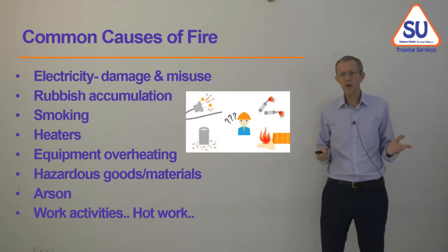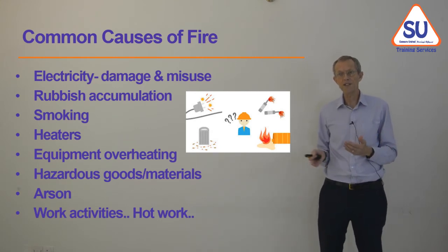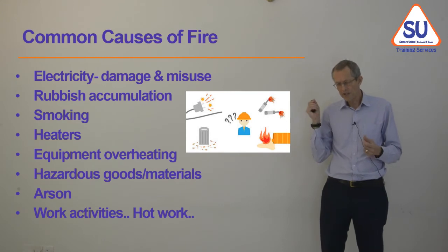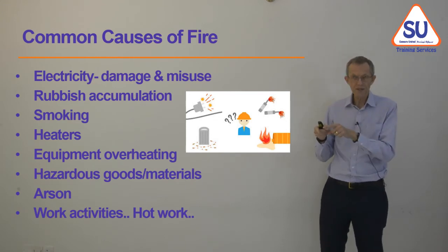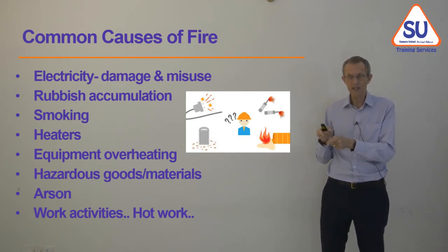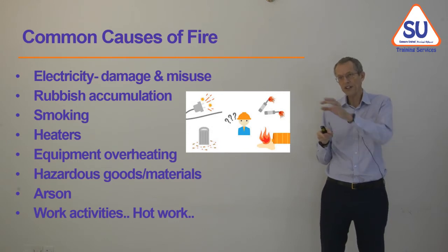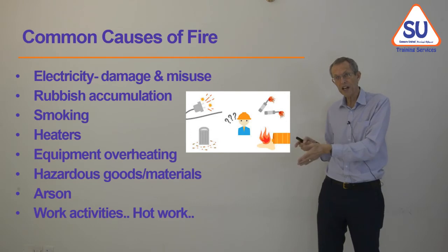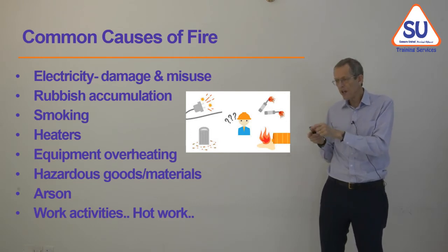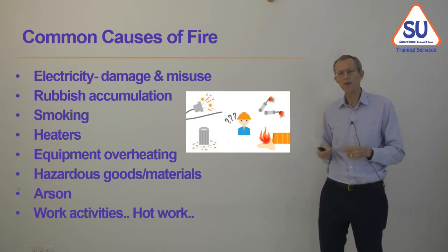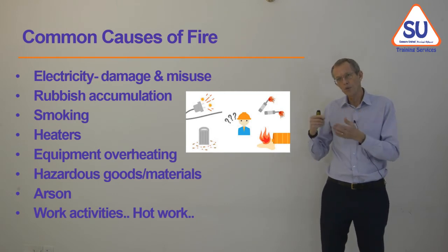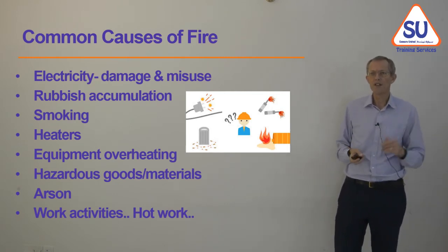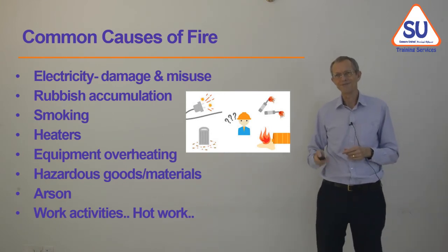And then we may have work activities that are high risk for fires. So if we do welding, when we strike the arc, that's a hot arc, very hot arc. The sparks from the welding can travel to other materials. So if I did the welding on top of a carpet, the sparks might catch on the carpet and the carpet would burn. Or welding is one, grinding is another, produces a lot of sparks that can catch fire.